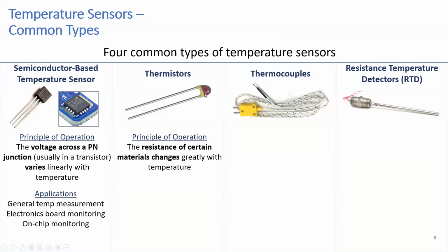I often like to say thermistors are just really bad resistors, right? Because normally you want a resistor to maintain a constant resistance over temperature. So maybe the gain in your op amp circuit is constant over temperature. But these thermistors are designed so that the resistance changes greatly compared to regular resistors over temperature.